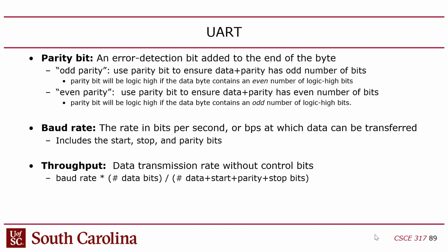Now, the problem is how fast do I read? What is the interval at which I gobble a bit off the channel? Well, that depends on the baud rate. I'm assuming that my understanding of the baud rate matches the sender's understanding of the baud rate. If they both match, then if I read at 9,600 times per second, for a 9,600 baud channel, I should get all the bits. But I'm just taking this on faith because there's no clock in the channel, so I just have to read at the rate I want to read at and hope that I'm synchronized with the channel.